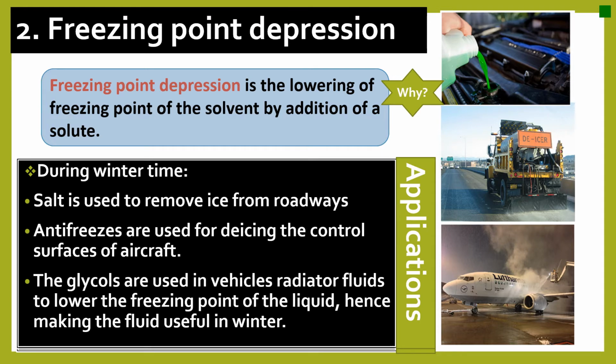The glycols are used in vehicle radiator fluids to lower the freezing point of the liquid, hence making the fluid useful in winter. Otherwise, when it is in winter, it's very cold, and then the liquid that is in the car radiator, special water, would freeze up. But when you add glycol as a solute, it lowers the freezing point, and even though it is very cold, the liquid in the car radiator does not freeze up.